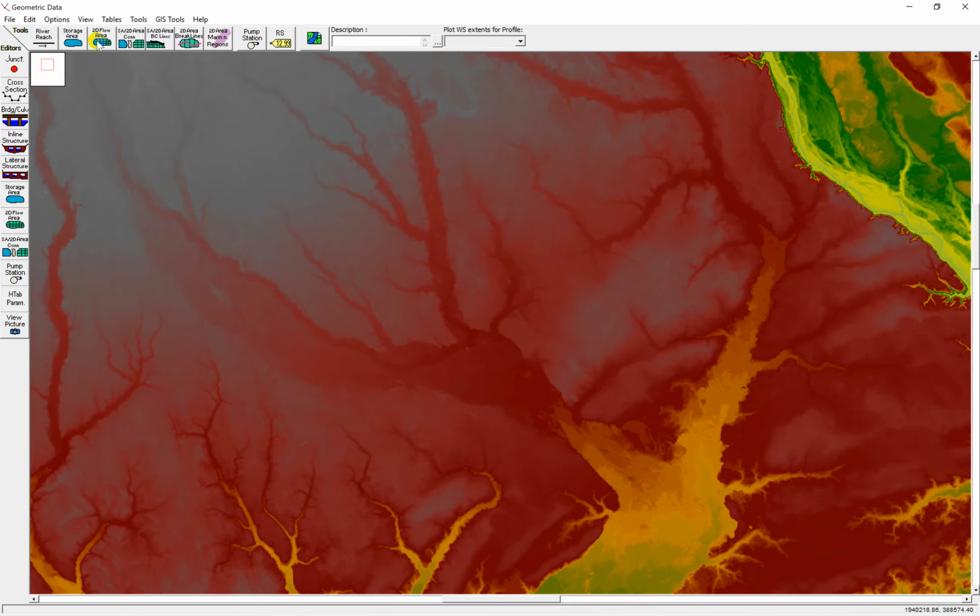So let's say that I'm going to create a 2D flow area. I click here and it will start from this point. I'm going to click and go up to here. It doesn't need to be very accurate, but you know the points where you know the discharge. This is a point, this is a point, this is a point. But the water is going to flow here. You can go straight, but I'm doing it this way because you have to confine all the water, because if the water goes outside, it will not come inside again.